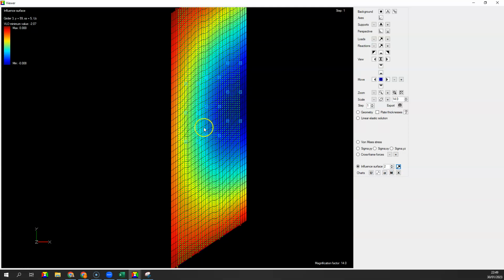displacement at that node is obtained when we have 3 lanes loaded. So here the multiple presence factor would be 0.85, and of course we have a point load here that's very close to the minimum of the influence surface. The other on the design lane adjacent to that other lane, we can see here that we have the truck located right here, and finally for the third design lane it's right there. So overall we have 6 times 3 equals 18 point loads, and the maximum displacement, well, I should say the minimum displacement would be about 2.1 inch.